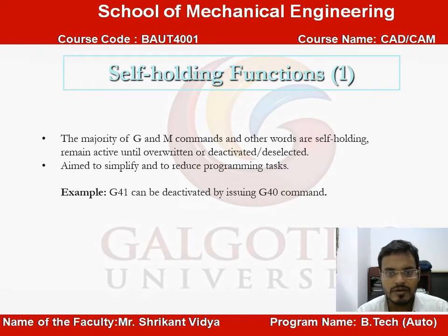Now, self-holding functions. The majority of G and M commands and other words are self-holding: they remain active until overwritten or deactivated. Self-holding means that unless the next command is written, the function stays active. For example, G41 can be deactivated by using the G40 command. Like this, there are self-holding functions.